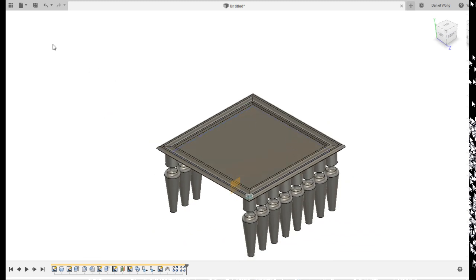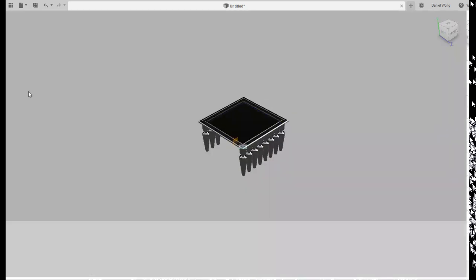And what we're going to be doing is going into the render workspace here. So for the first time ever, we're going to explore past model, and we're going to enter the render workspace. So let's click render, and it does its own funky thing. Okay, it takes a while to load. Just a preemptive warning, rendering tends to kill your laptops because it's a very process-intensive action. So it will drain your computer a little bit, but we can tweak those settings to make it not kill your laptops. Okay, and I'll show you those settings.